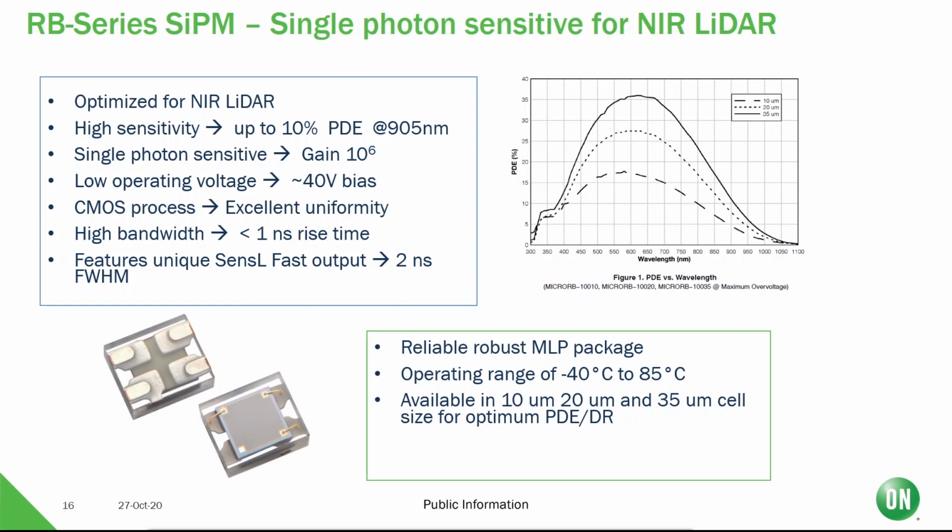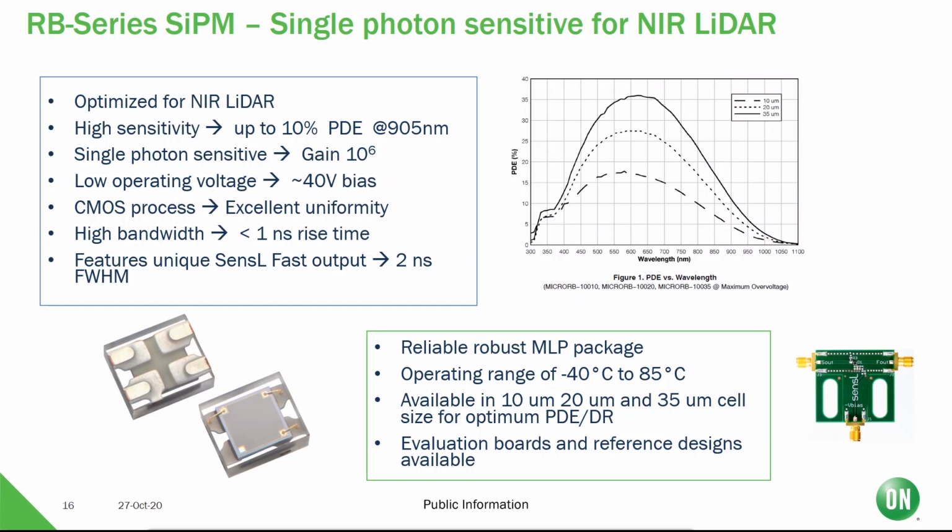This family of sensors comes in several variants. So you have a choice of 10 micron, 20 micron, and 35 micron microcell size, which means it's possible to trade off PDE and dynamic range to suit the application-specific requirements. And we have evaluation boards available.